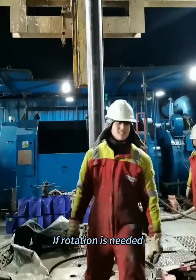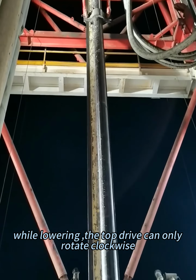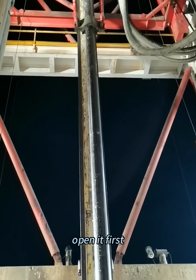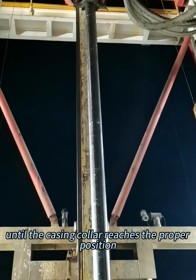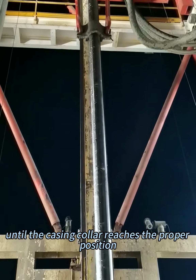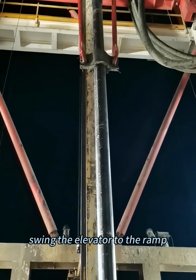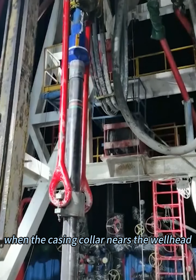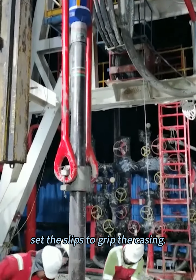If rotation is needed while lowering, the top drive can only rotate clockwise. When the elevator reaches the wellhead, open it first and continue lowering until the casing collar reaches the proper position. Swing the elevator to the ramp to prepare for the next joint. When the casing collar nears the wellhead, set the slips to grip the casing.